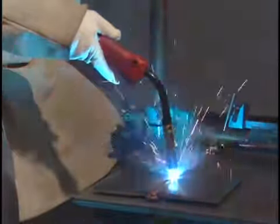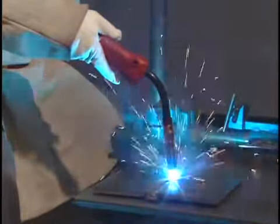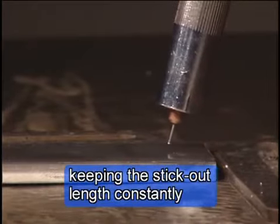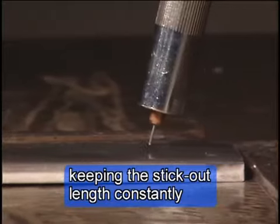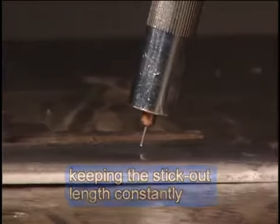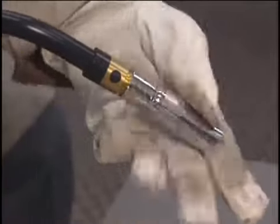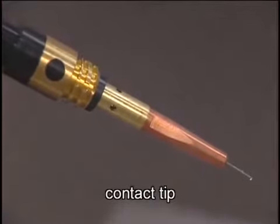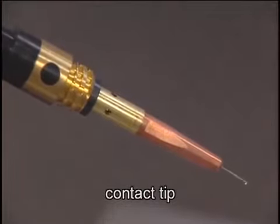The welding results are influenced largely by the handling of the welding torch. For example, maintaining a constant tip to work distance influences the quality of the weld results. The purpose of the contact tip at the end of the torch is to feed the electric energy from the power supply to the welding wire by contacting the wire to the inside surface of the torch tip. Then an arc is generated between the end of the wire and the base metal. This creates the molten puddle which joins them together.